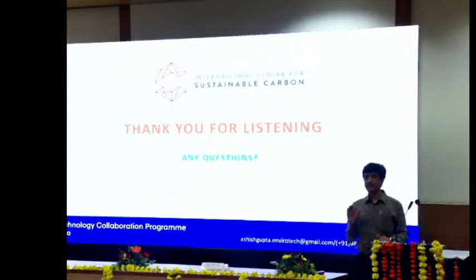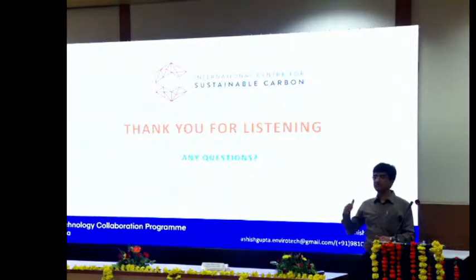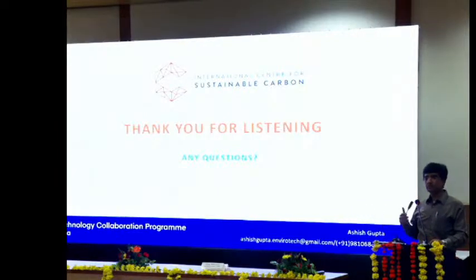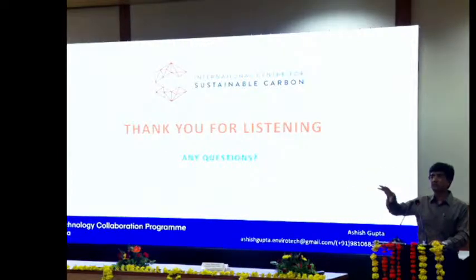So the idea of showing you all these exercises is that you should know how things are being carried out. Don't think of CEMS as only a black box. It does not give any value of its own, as I told you in the beginning. Whatever value you feed into the system, the system will start giving you that value. So that dust factor, whatever has been fed, the supplier of CEMS might have given it with their own experience or by taking some standard value.